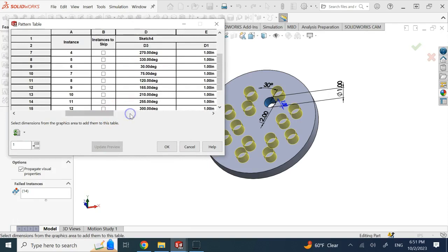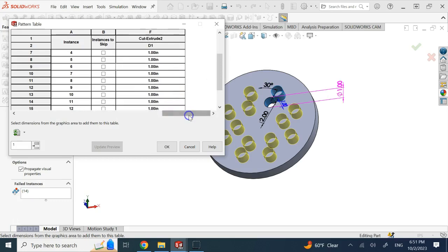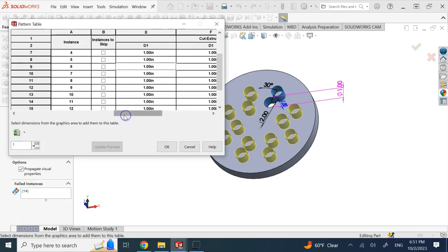And if you want for these 8 holes, you can go ahead and change the depth of the cut. So you see this 3.2 here, right? And 30 degrees. Maybe I want for that, which is, let's see which row it is. So it is row instance 6, basically.